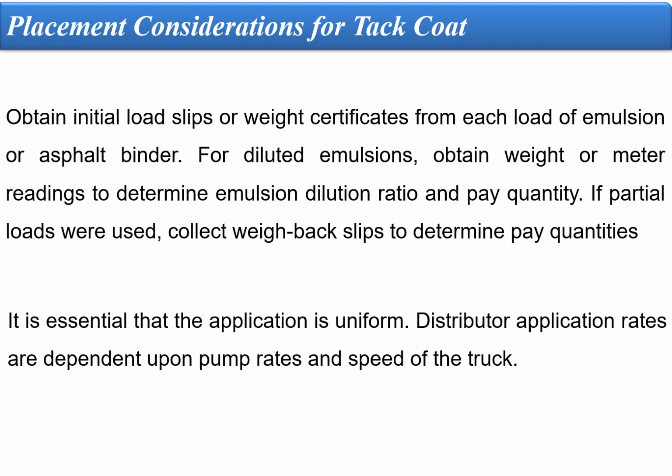Apart from the pay quantities, it is also important because it will tell you how much area you are going to cover with the tack coat, because there is a spray rate which has to be followed as far as tack coat application is concerned. So depending upon the quantity available, you decide how much area you want to do a tack coat application in the project. If that much area is not being covered, that means the weight of the material being carried by the truck is either less or your application rate is high. So it is essential that the application should be uniform.